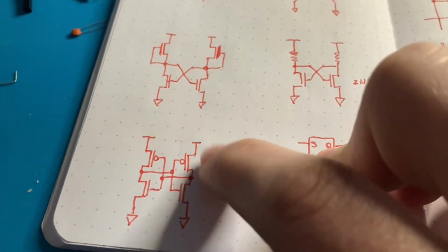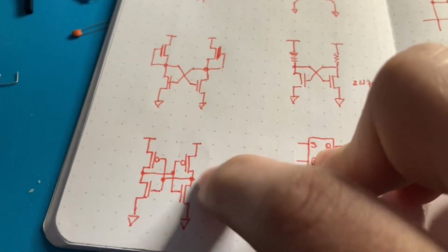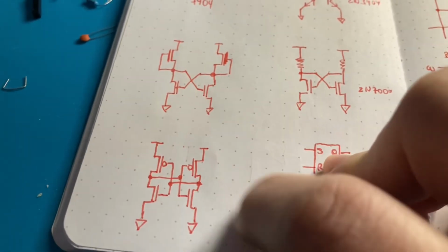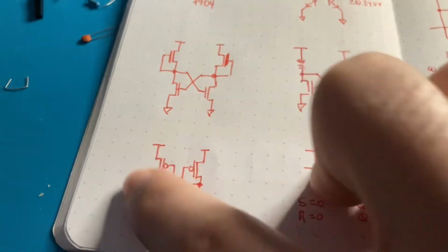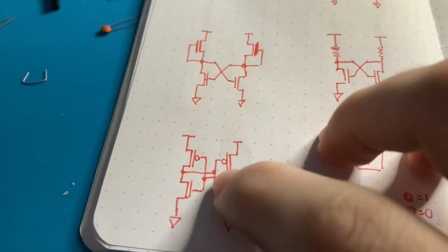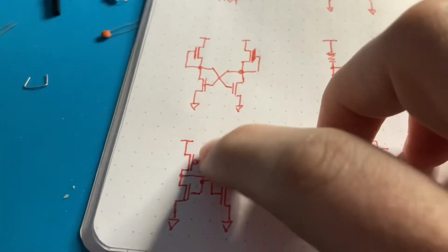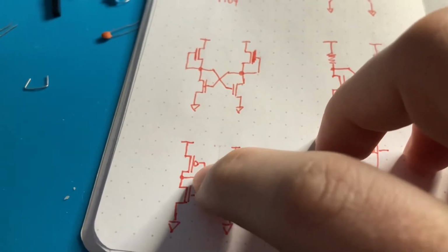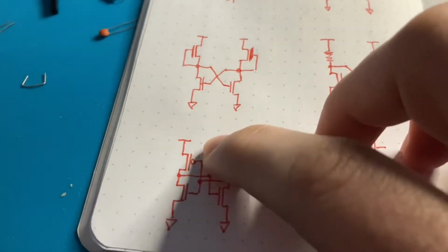because it doesn't really conduct. It only conducts when the output changes; there is no load here, in a nutshell. So in the NOT gate of a CMOS, there is no load. The input pulls to either side.